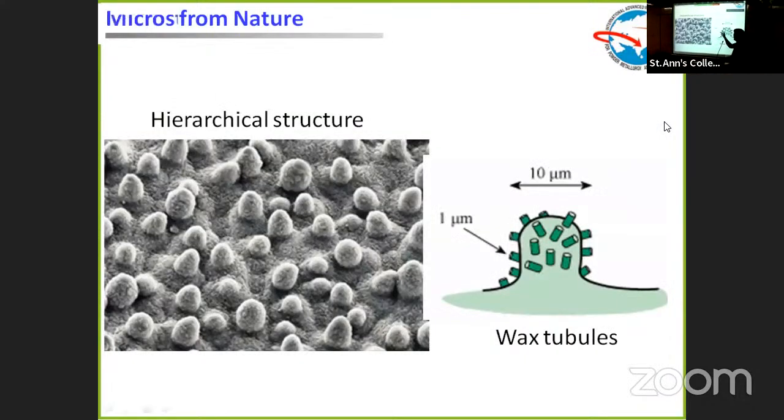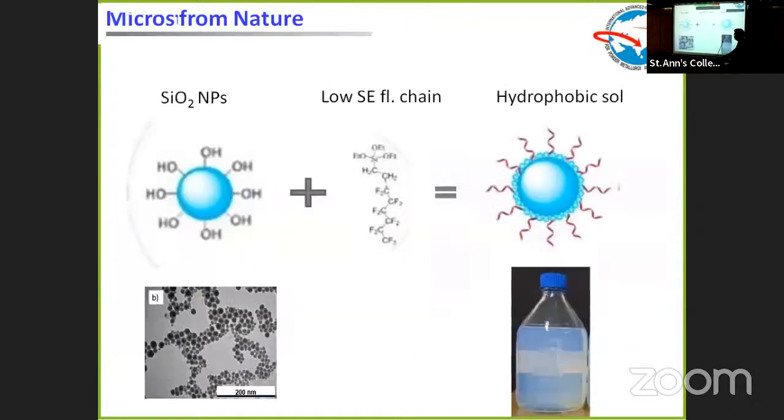If you go further into the microstructure of the leaf surface, it is made up of two different structures. One is micron-size spikes, and the other is nanometer-size roughness. These two things contribute to the hydrophobicity, which means the water contact angle. This structure repels the water from the surface, and the water tends to roll off. During this process, dust is removed by natural means. There is no need for external force or any solvent or water for cleaning the surface.